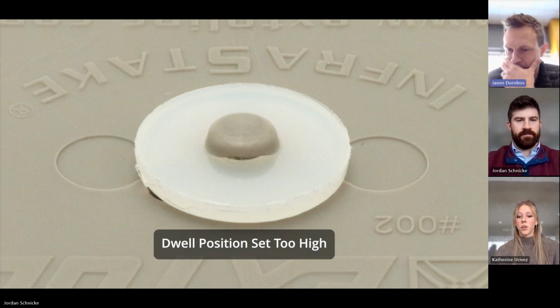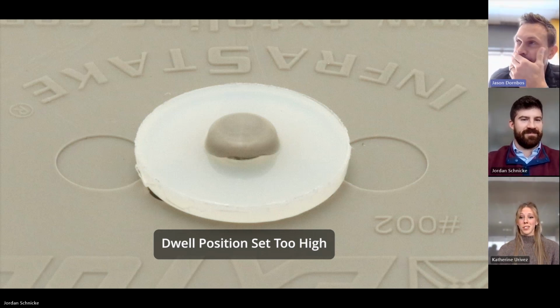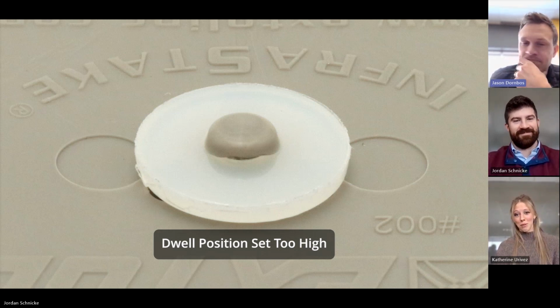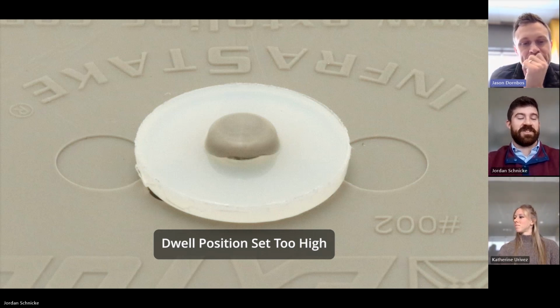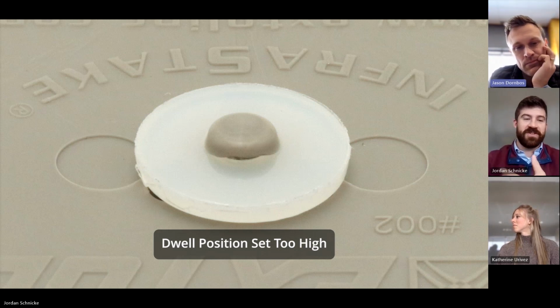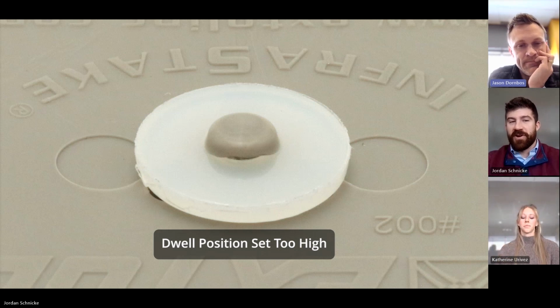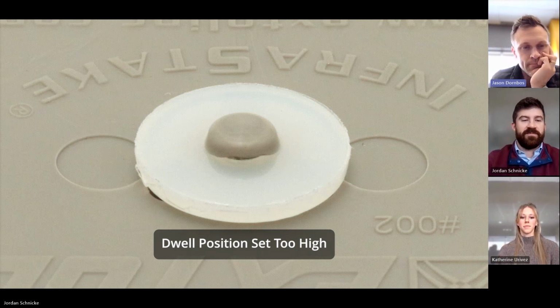So that's a case where your dwell position is set too high. Your cycle time was probably pretty quick because you weren't melting all the material that was supposed to be there. And in some cases that might be acceptable. It's really up to you guys to determine if this is good or not. I would say 9 times out of 10, it's not. This will also affect the overall strength, right? You're not melting all the material that's present. It's going to have a weak spot.